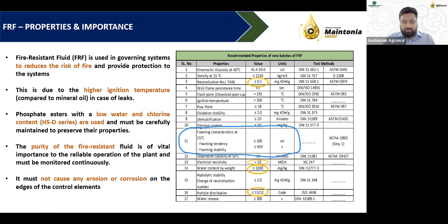Why does this foaming happen? I remember we had a webinar a few weeks ago on foaming and air release values. It's very important to understand why this foaming happens and why this foaming is sustained in the fluid. When you have turbulence in any system, bubble formation will happen. You can't actually suppress the bubbles by some external force because it would lead to a lot of equipment accessory attachment to your system.